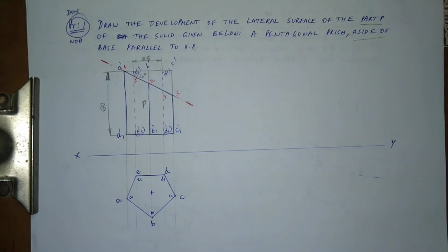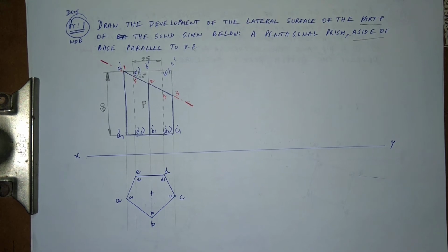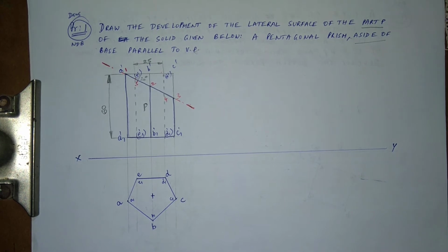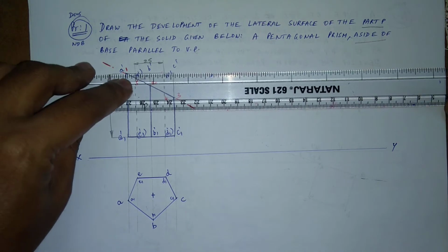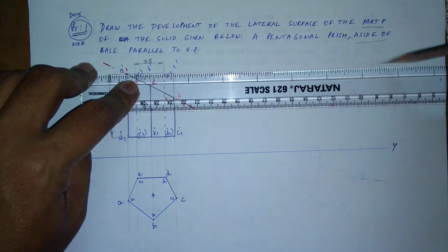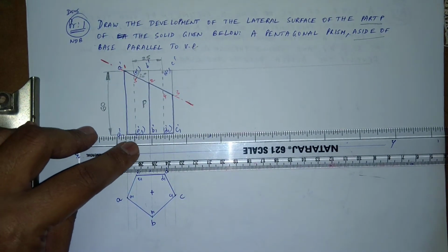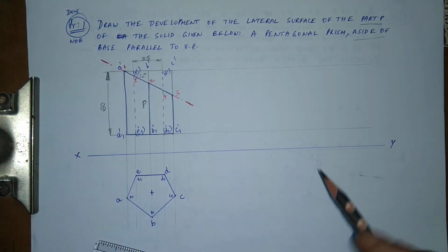Now since it is a parallel line development, I have to draw the parallel lines from each of the points where the prism has been cut. This is what I'm trying to do. Alright. So let me just develop out the base surfaces. I'm using a pencil here. So these are the parallel lines I'm using. All I'm doing is drawing a parallel line from here, very lightly. Okay.